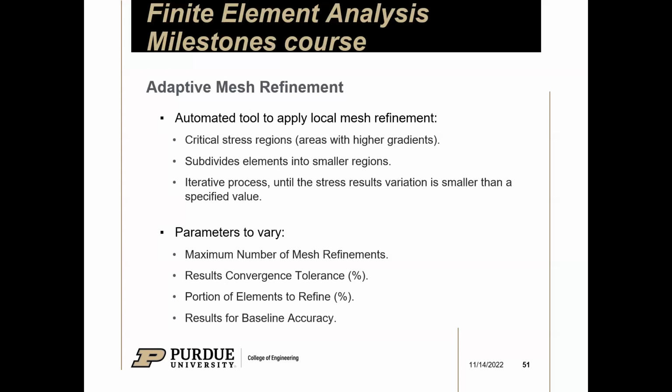So that will be our most critical point of the model, right? So the system will look at that, and the top 10% of the model, which mostly will be that edge, will go through further refinement. Everything else within your model will most likely stay about the same, even though it goes through a bit of refinement where it gets a bit more accurate, but it won't go through as much change as that critical point.